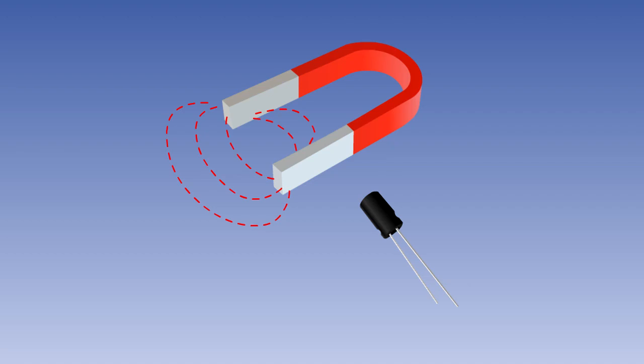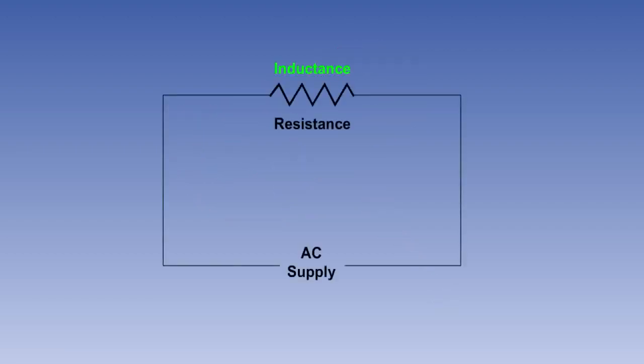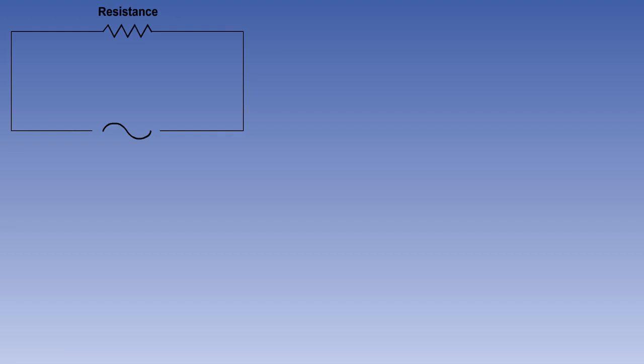In most AC circuits, because of the ever-changing values of voltage and current, the current flow is influenced by the magnetic and electrostatic effects of inductance and capacitance. There is no such thing as a pure resistance when considering an AC circuit. All resistors, even a simple piece of wire, have a property known as inductance as well as resistance. However, for the purpose of studying AC theory, we will assume that we can build separate circuits having only resistance,